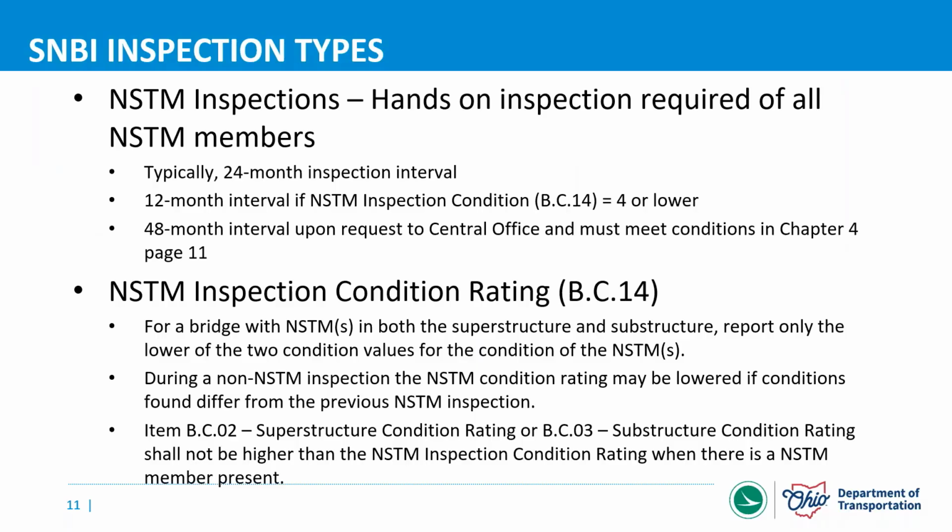So if you think you have NSTM inspections that are very tedious, very costly, maybe it's over railroads that's very difficult to work with, etc. If it would benefit your organization by possibly having a 48-month NSTM inspection, please check those conditions in chapter 4, page 11, and see if your bridge can meet those conditions, and then those will be submitted on a case-by-case basis to central office for review.